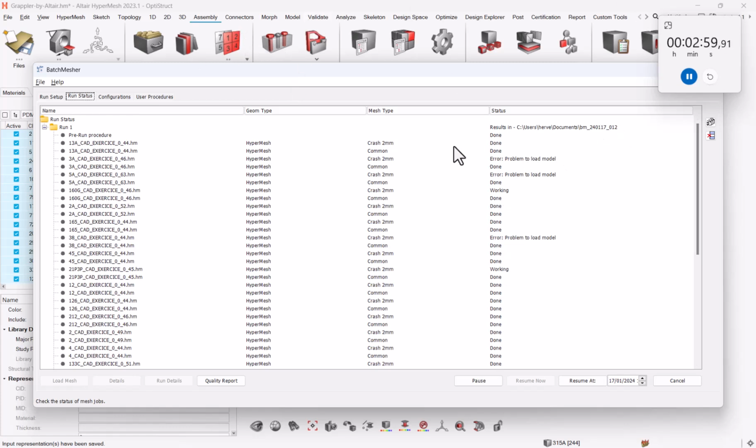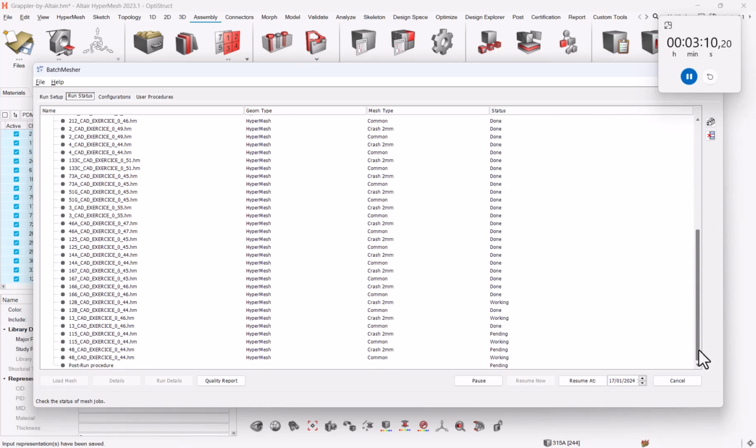So just to catch, there were some errors meshing some of the parts. So we'll see later on how to detect them in HyperMesh. But yeah, you can capture these ones and see why, or at least identify which one failed. So we're close to getting the final delivery. There are still 4 meshes to be done before completing the mesh.